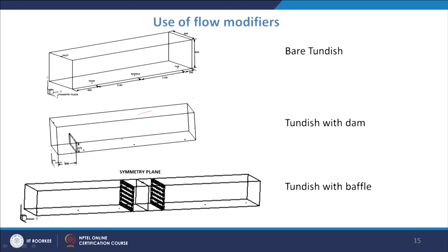So, for that we use the dams. We also use many a times the weirs. Weirs are used from the top and at a certain height. Then we also use the baffles. Baffles will have a limited outlet area in that whole domain, so through that the metal will pass. So, dams, weirs, baffles, and even the advanced pouring boxes are designed on the bottom wall and just below the inlet, to see what their effect is on the flow alteration.